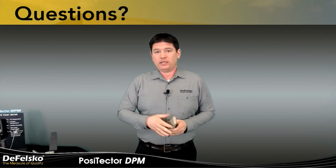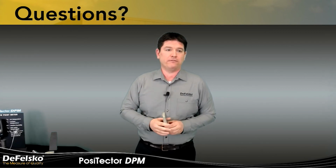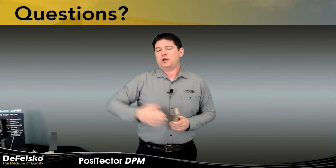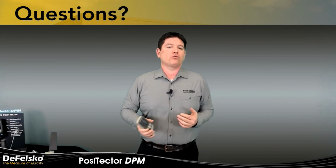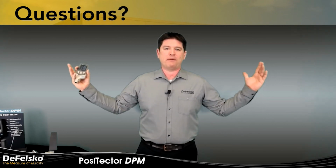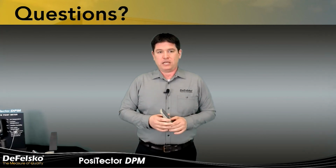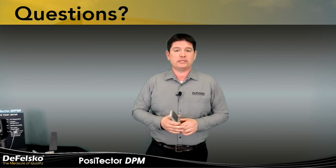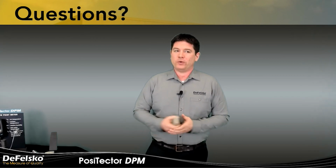And that's really something that a specific customer would just have to know ahead of time before they tried to take a reading that was 30 or 40 yards away. It's just not going to give them the greatest temperature reading because it's averaging a very large spot. The closer you can get, the better it's going to be. But just keep in mind, it will read quite a ways. It's just going to average that whole area. I hope that answered your questions.